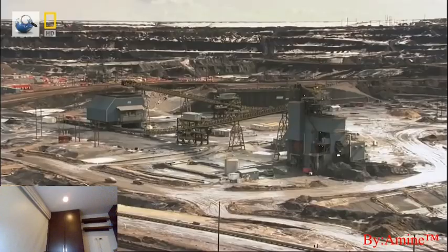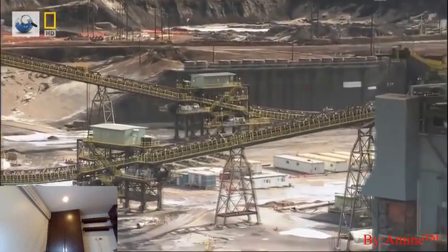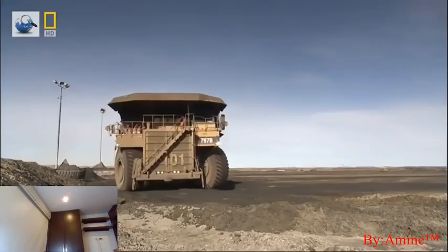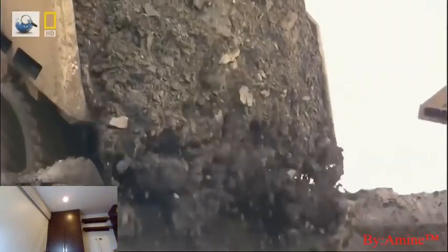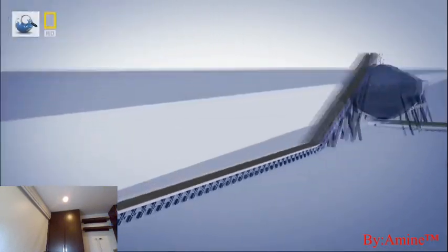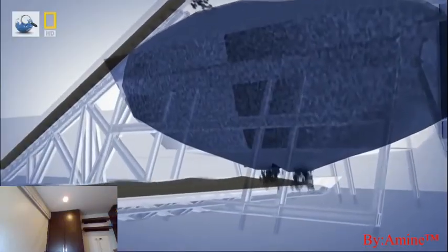The last leg of the journey begins here, at the train. That's the name that Syncrude has given to an innovative and expensive state-of-the-art transfer system. The train is composed of 3 parts. First, trucks dump their oil sands into gate-mouthed crushers that mince large chunks into bite-sized pieces. Next, the loose sands fall onto a powerful conveyor belt that transports them to a surge bin. It looks like a glorified funnel, but it is actually the heart of the transport system.